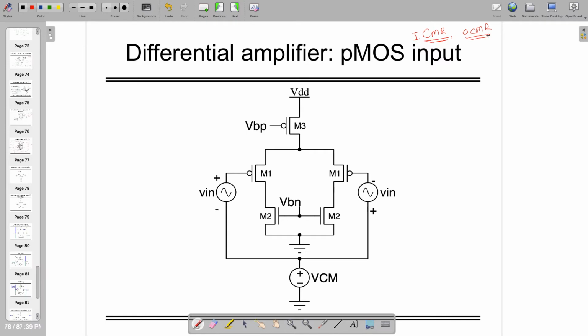Now what I'm using as an example is having the pMOS input. As I was explaining earlier, if you have a differential circuit which has the pMOS input, you might not have the current sink, but you are going to have the current source. So these two are identical, balanced networks. They are connected with some wire. Then this becomes VP as AC virtual ground when you are applying the differential inputs.